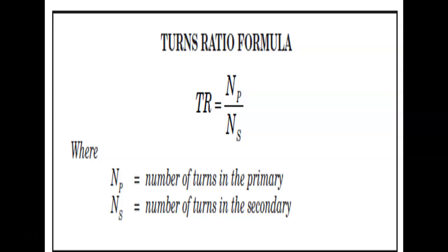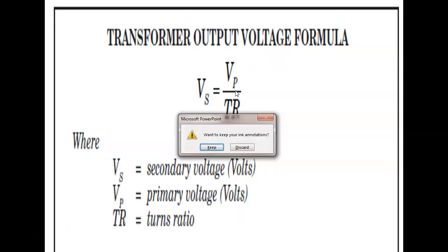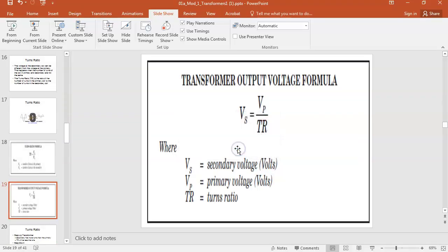Technically we could bring 480 in here, and if you divide 480 by 4, what will you get out of it? 120. Or we can bring 240 into it and divide it by 2, and we still get what? 120. But what we do is rewire the transformer. You can see this is a dual voltage transformer, and we're going to do it manually. We're going to use jumpers on our transformer.